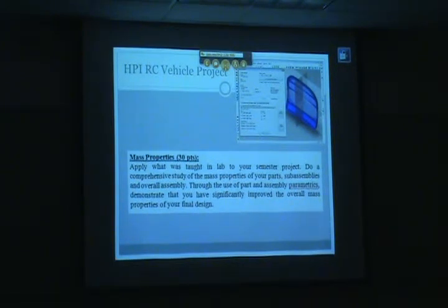yet. Mass properties, we will do that on many of the individual components, and we will ask you to calculate what your overall weight of your car is. And we're hoping that what you find is that the weight of an individual component as weighed by a scale is very close to the weight that the CAD system predicts it would be if you put in the right material properties. Okay?